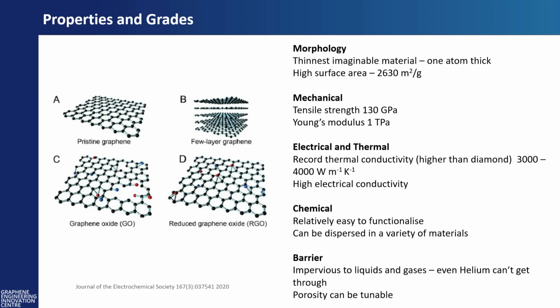Essentially, graphene is strong. It's got a huge tensile strength and a huge modulus for its size. It's completely disproportional. It's incredibly conductive. It's one of the most conductive materials ever. Despite what you might see on the internet, it cannot hold a baby elephant. It's not stronger than steel. This is the general fight we have all the time, because there's lots of sensationalism around graphene, the wonder material. You know, it got a Nobel Prize. Where did it go? Why is no one using it?